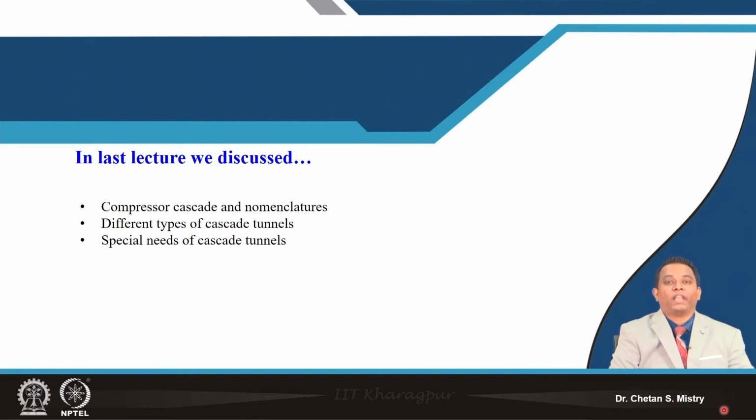And we realized our blades are made for particular angles which have already been calculated. Because of my inflow condition, it is possible that the flow will not be incident at the design angle, and will be striking the blade leading edge at another angle, and that's what we have defined as the incidence angle.